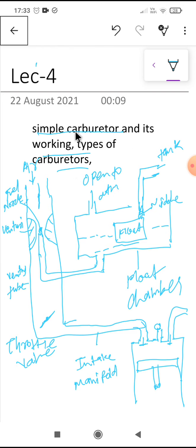Let's now see. This figure will give a nearly constant air-fuel mixture. It consists of a float chamber, needle valve, and fuel nozzle. During the suction stroke, the air at the inlet from the air filter is at atmospheric pressure, and in the cylinder there is a vacuum.